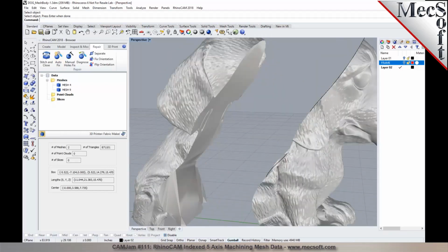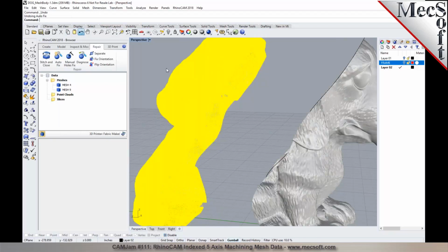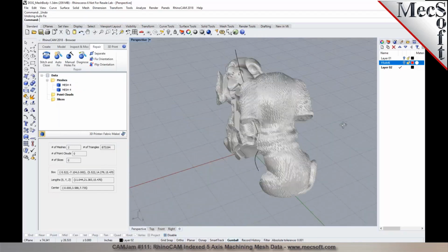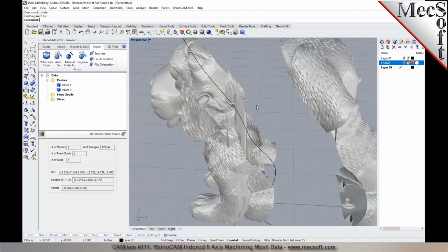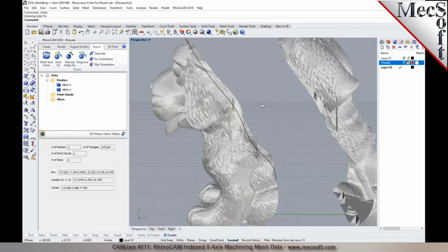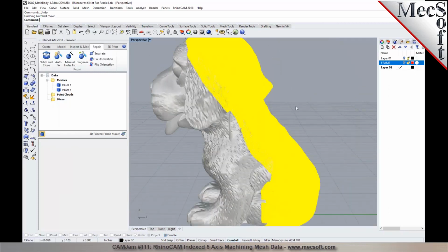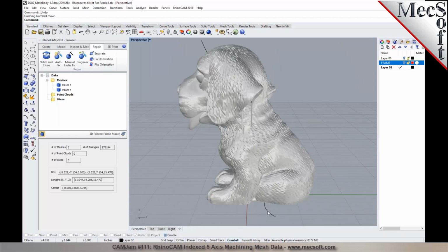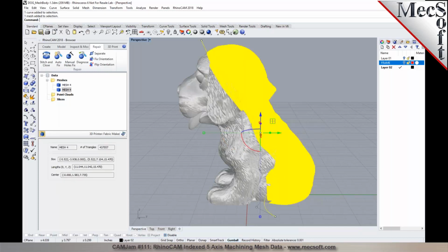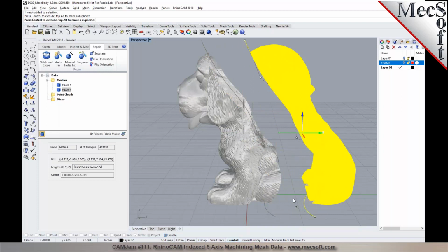But then if you want it to be smooth and stuff, you can even model a surface, trim it with that, and then you can fix it. So I can show you one of the other ways how you can do it. So for example, let's take this curve in here. Let me undo what I just did. Okay, so I'm going to take these two. I'll make a copy of this. I'm going to select this one too. And I'm going to drag it out by a certain distance right here.